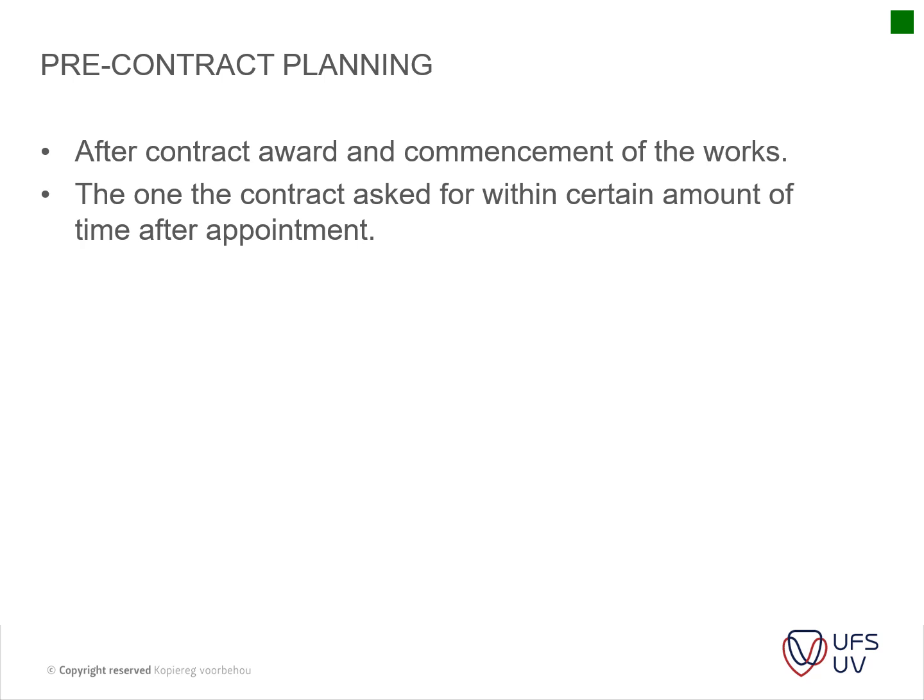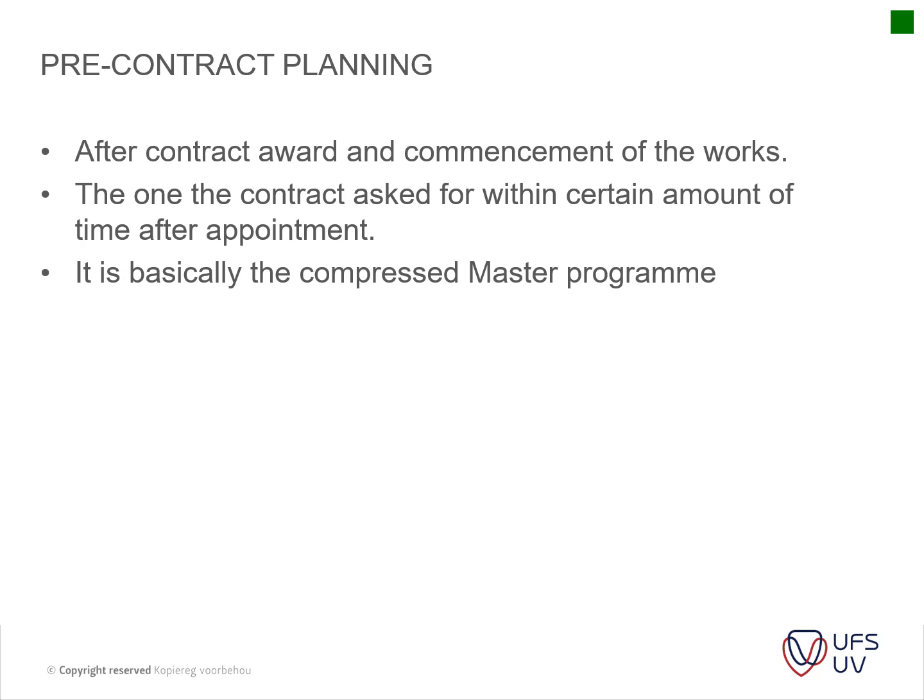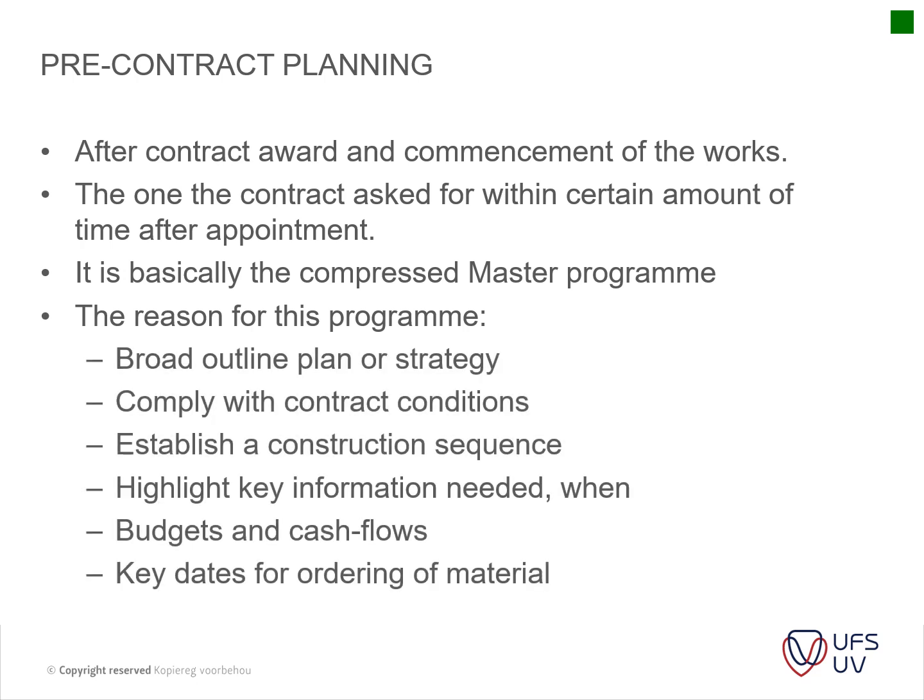The contract asks for a program within a certain amount of time, that's what I just talked about. It's basically the compressed master program that you need to look at. The reason for this program is a broad outline plan of the strategy. You have to comply with the contract conditions, as the contract asks for that. It establishes a construction sequence and highlights key information needed and when, and budget and cash flows obviously go with that also. Key dates for ordering of material are set within this time period.